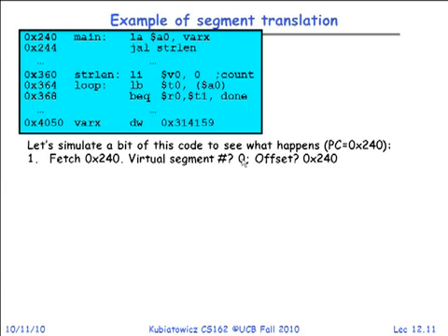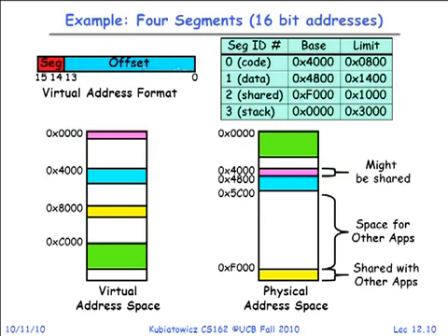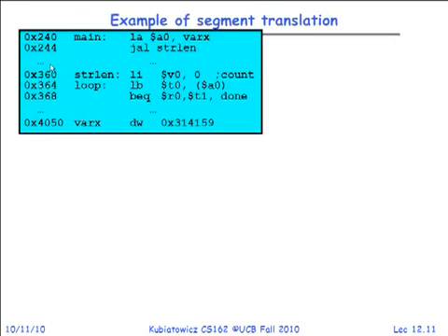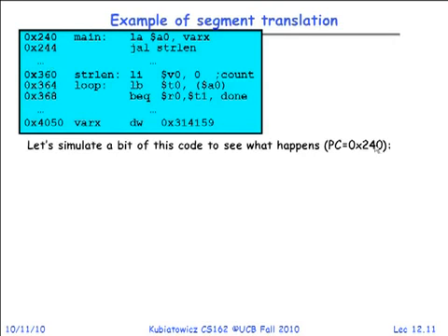Yeah, so remember we're working in this space, so we're taking our 16 bits and thinking about those top 2 bits. If we think of our 16 bits, that's four nibbles, right? And the top hex digit here is 0. The top 2 bits of that 0 are zeros, and therefore our segment is 0. Can you guys all do that sort of translation in your brain?